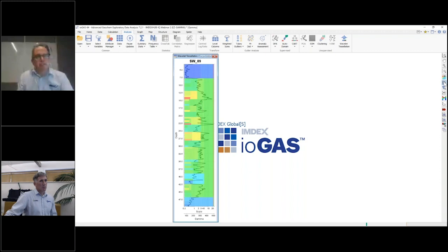We can filter at different levels. What this does is it filters based on the strength of the boundary or the feature at the lower scale. So if we increase this, we start to lose some of that fine detail that's likely more noise than it is features in the gamma data itself. We can also change the coloring mode from just a normal linear coloring scale to a log coloring scale or percentile coloring. And this is good if you want to highlight certain features.